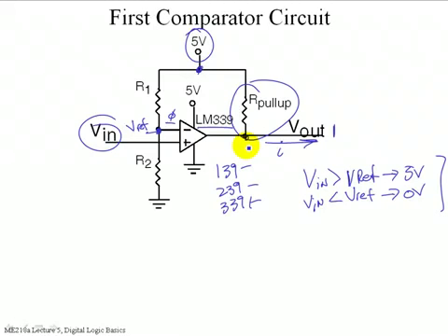Hypothetically, if Vref is equal to Vin, what happens? Could it ever be exactly equal? No. So that's the answer to your question. There's an infinite gain being applied to 0 input, then it would be 0 output. But it's a situation that physically cannot exist. And so we can do mind experiments, but they're not very useful in terms of building circuits. Yes?